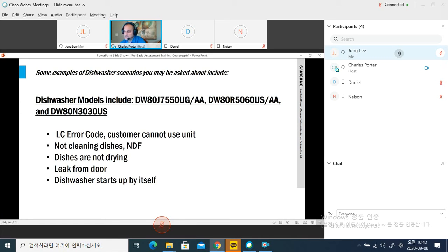Even though that's on the back side of the unit, the water can roll down into the bottom of that unit and trigger that sensor as well. So a whole bunch of places you can check. What are some things that cause it? Obviously, if the hoses are broken, or where the hoses connect to things, those clamps are not tight, something along those lines. The unit could not be level.